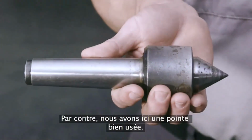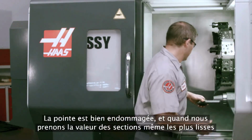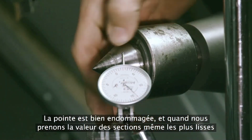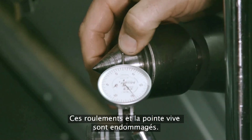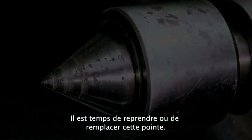it's supporting. In contrast, here we have a well-worn center. The tip has significant damage, and when we indicate even the smoother sections, we get jumpy indicator movements. These bearings and the center's tip are damaged. It's time to rebuild or replace this center.